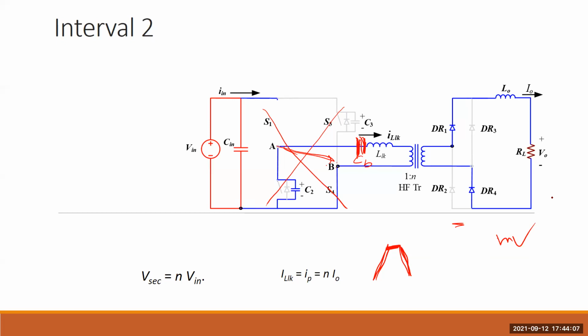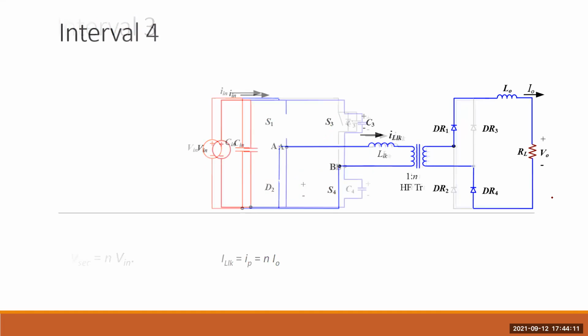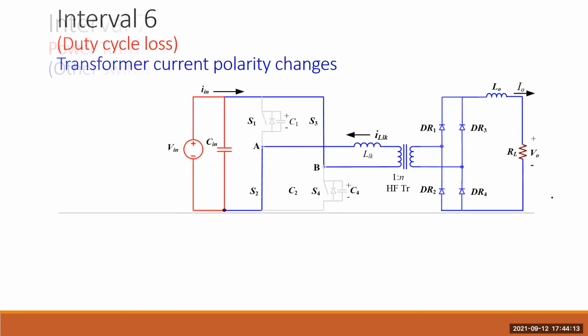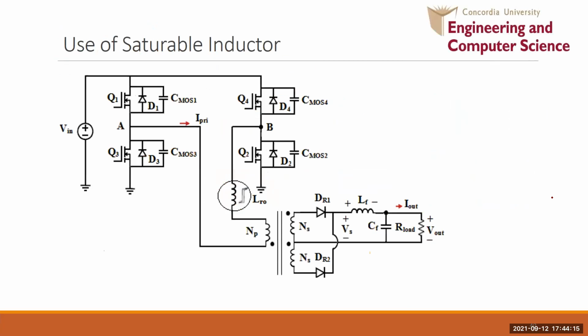So this is the saturable inductor. What are the criteria to be considered when selecting this one? Mainly two things. One is the resistance of the saturable inductor core, because it will cause loss. Another is cooling, because at full load or near full load the saturable inductor core is saturated with current passing, so it will be heated.